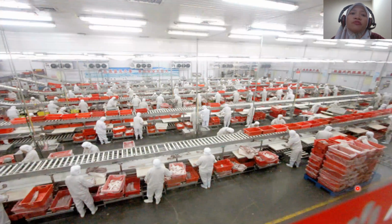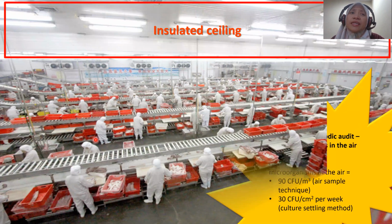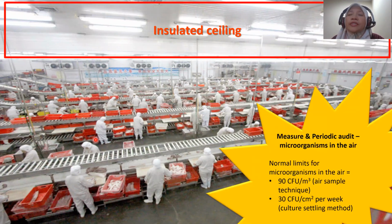A good precaution to avoid hazard from condensation is to install insulator layer. This insulator layer covers the cold lines in the ceiling of the factory. Some industry install trays with proper drainage underneath the cooling equipment. If let's say there is a product line under the cooling equipment, there are standard or legal requirement which required food industry to measure the microorganism in the air and to conduct a periodic audit.